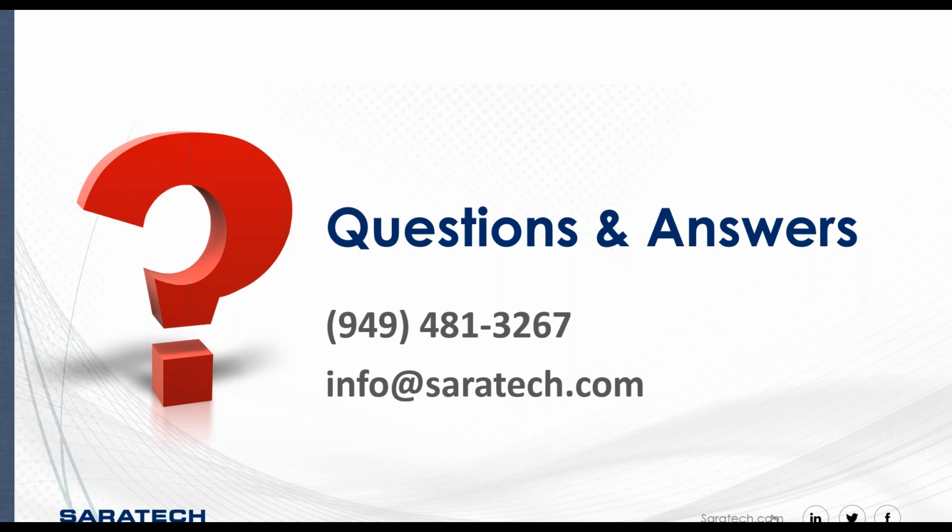Nice, thanks. And our last question is, can I store feeds and speeds for tools in different materials? Yes. So feeds and speeds for different tools and different materials can be stored either in the technology database or even in the user interface. There's the ability to save proven feeds and speeds to the database and to the user interface, so that whenever you pick a tool and you're in that material, it will automatically select the correct feeds and speeds for using it, and even depth of cuts as well.